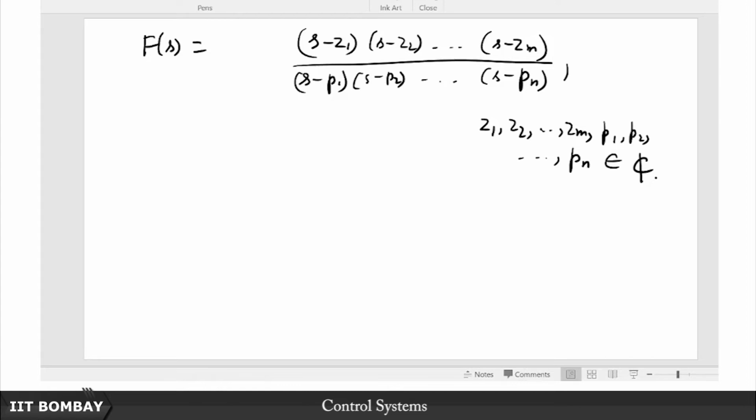So far as this factorization is concerned, here after all we are not looking to get the inverse Laplace transform and things like that. That is when we kept those conjugate roots together, because we wanted only real factors in some cases, right. But here we do not care, this is just an analytical tool for our analysis. So here we can factorize this polynomial in the numerator into linear factors if we allow the complex factorization over complex numbers, and similarly the denominator can also be factorized into linear terms like we have done here.